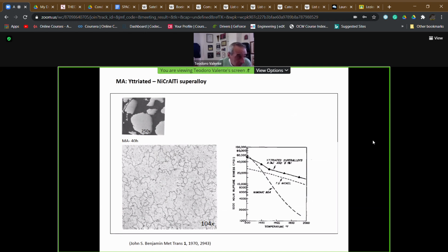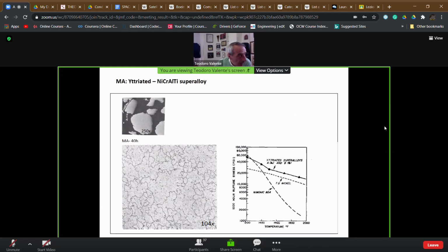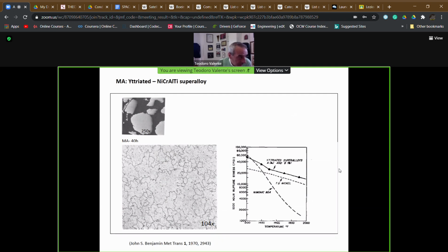We must remember that this kind of creep is not the only one existing. We also have diffusion creep, for which we have the possibility to contrast the permanent deformation by using single crystal technology. Well, single crystal technology cannot be used in this case with ODS materials; it can be used just with the already known nickel-based superalloys, with controlled solidification.